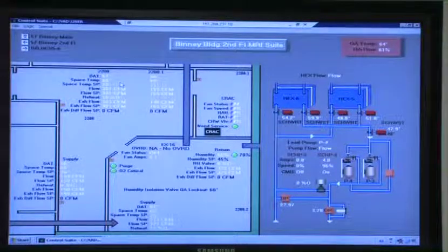So I understand, because I have to understand this now. 2208 is the room that it's in. This is this room here, 2208. You're telling me that there's a VAV box. This is the information off a VAV box. You can actually click on the T-stat right next to it, and it's going to take you to the same information, to give you the max and the mins on the set point, and the typical box information.